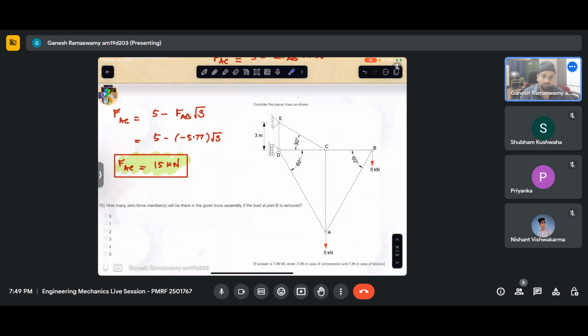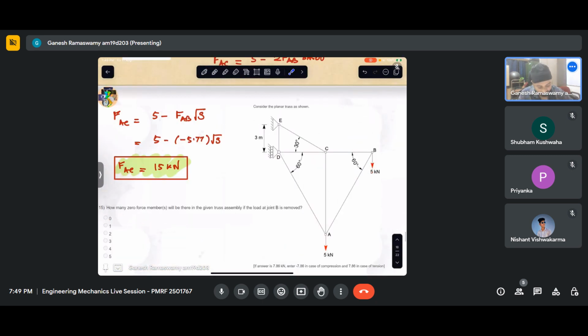So are there any questions based on what we discussed? Anyway, one interesting thing we are able to see is that this is redundant information. Even if this is not provided, we are able to solve for the unknown forces. That is an interesting thing to note. What that implies is these angles are enough to preserve the geometry and to define how force distribution will take place. So either this or this could have been omitted, and we can still find out the member forces. So it is redundant information.